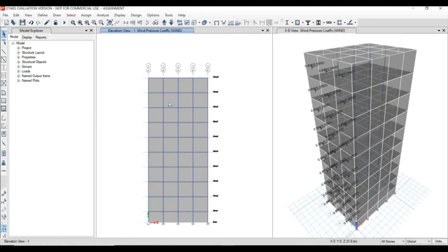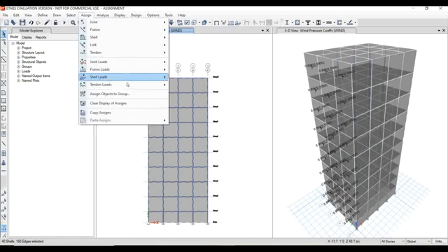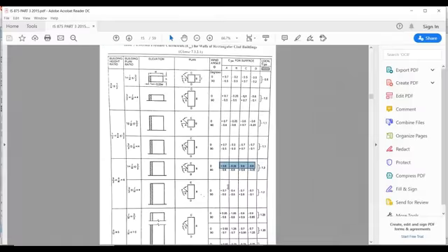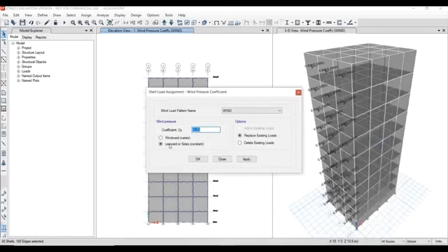And now click every shell so that we select it. And now we need to assign shell loads, wind pressure coefficient, and for the wind pressure coefficient we have minus 0.8, leeward direction or sideward constant. Okay.